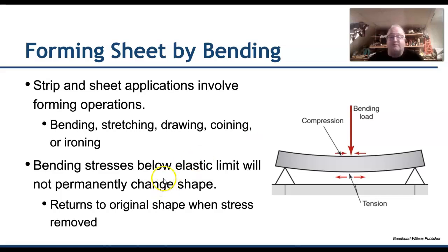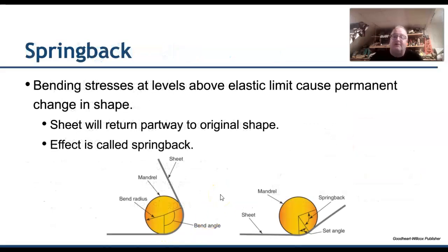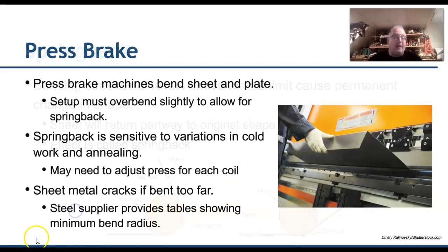Those of you who are involved in fabrication, or those of you who have machined and fabricated the sheet metal tool tray, know and understand as we use the press brake to bend that. Especially if we're bending at 90 degrees, oftentimes when we bend to 90 degrees and then release it, it pops up and is open. The sheet metal is still at a greater degree. So sometimes we have to overbend a little bit to make sure that it stays at 90 degrees. And of course, that's what we refer to as spring back in the actual material, and we have to pay attention to that.